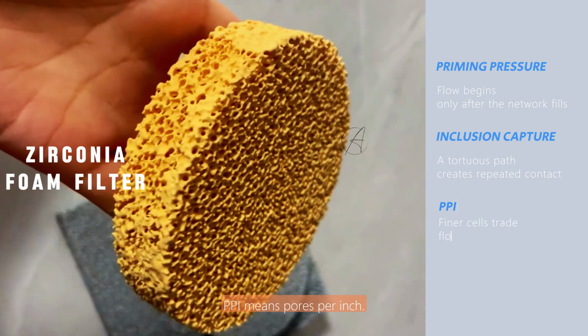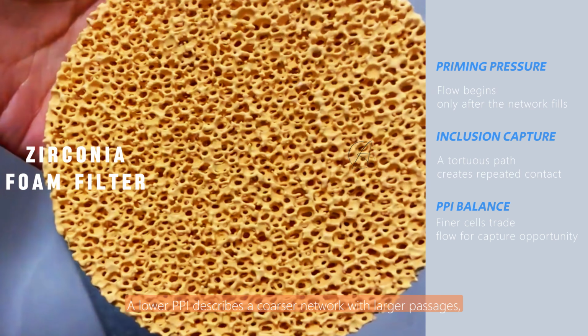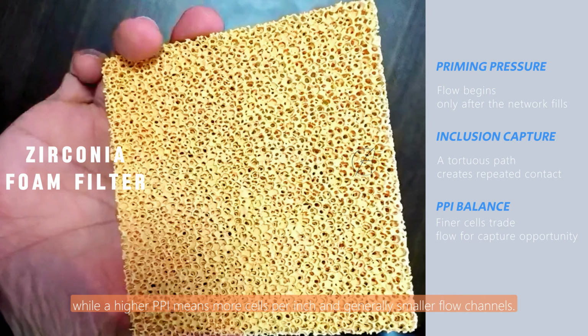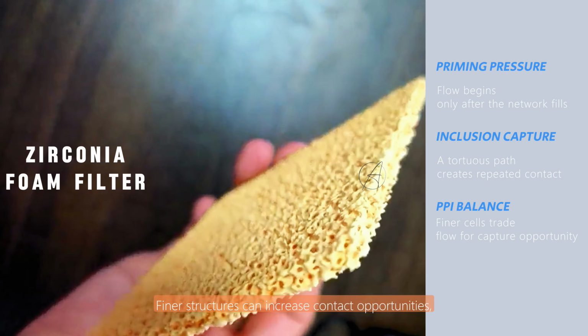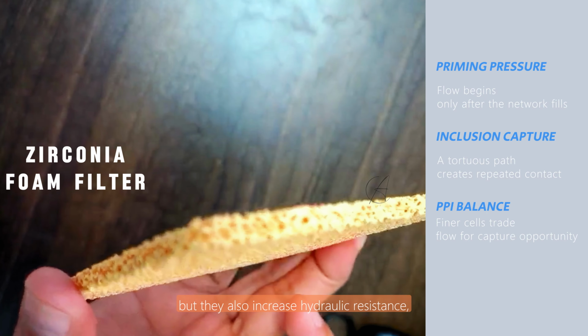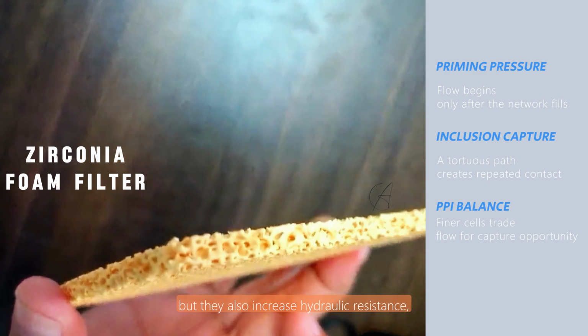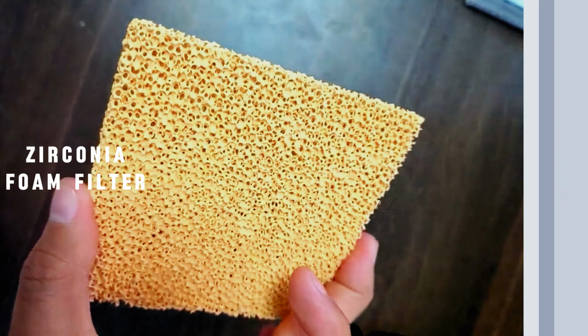PPI means pores per inch. A lower PPI describes a coarser network with larger passages, while a higher PPI means more cells per inch and generally smaller flow channels. Finer structures can increase contact opportunities, but they also increase hydraulic resistance, so the highest PPI is not automatically the best choice.